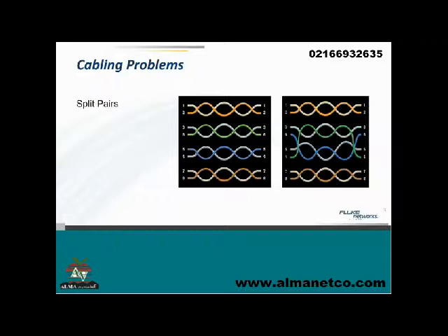And obviously, if you ran into some problems down the road and you brought somebody in to look at it, they might go, well, it's your connectors. That's the problem. So that's an interesting thing to think about. But remember, in order to legally make a Cat 6 link, it has to be made of all Cat 6 components. And that's true with any of the standards.